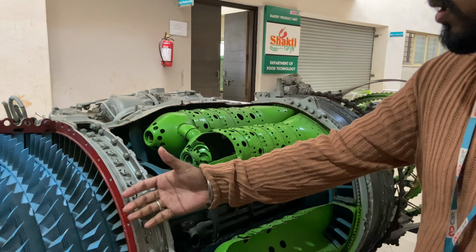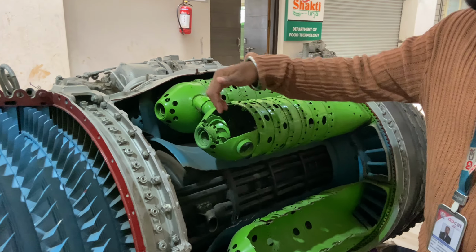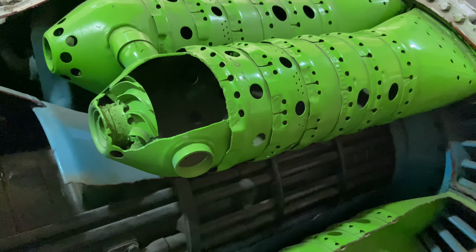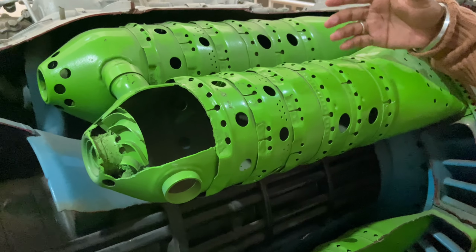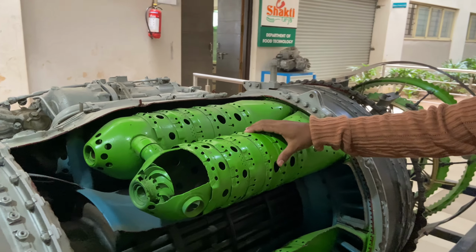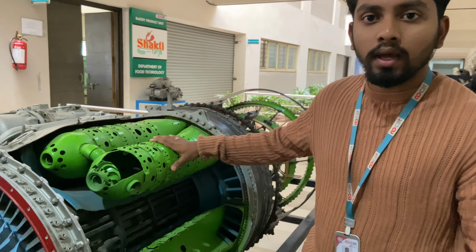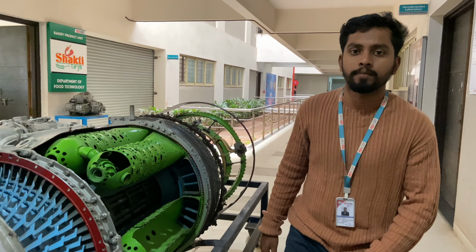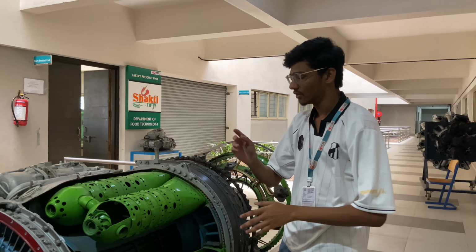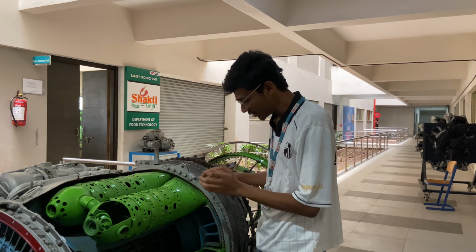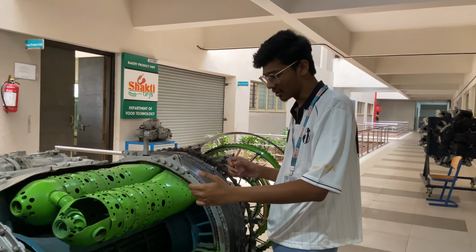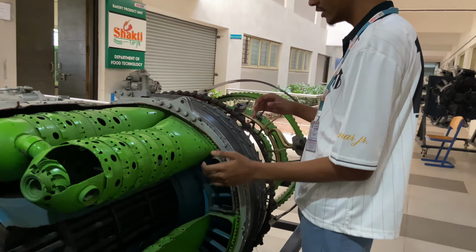The air comes to the front of the engine and goes through the diverter, which diverts the air and rotates it. Now the fuel is injected from these holes, and the mixture of fuel and air is mixed inside and ready for burning. After the combustion chamber, there is a stator. It makes a streamline from the fuel which is burnt. The burnt fuel goes to the nozzle part.